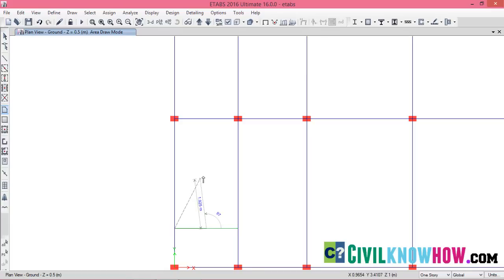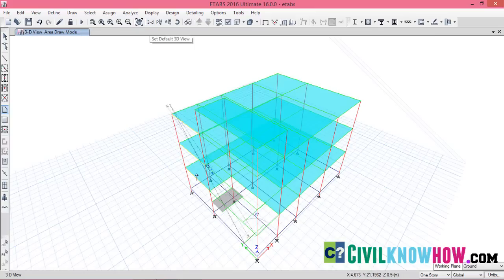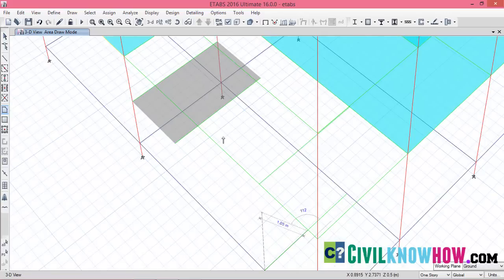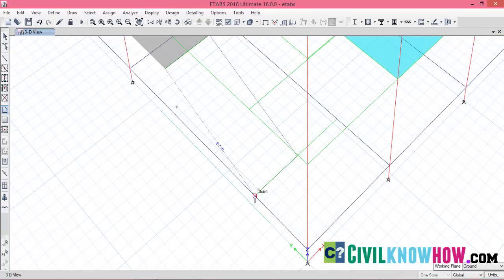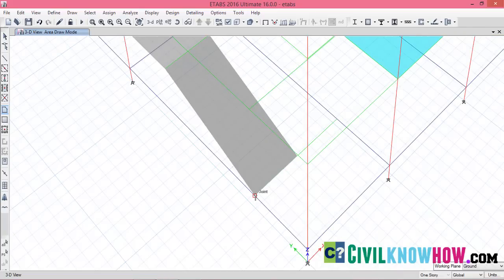and now I need to go to the middle floor. So I'm going to take the 3D view. This is quite a bit messy, but still it's a good option, and join over here in this middle point and connect it to the other adjacent point, and then come back to the ground floor. So your first stair flight is ready right now,